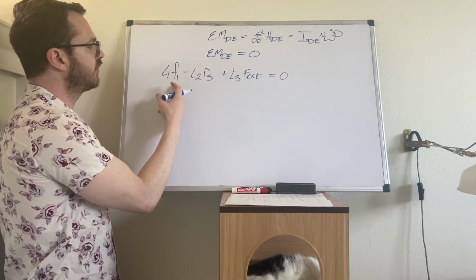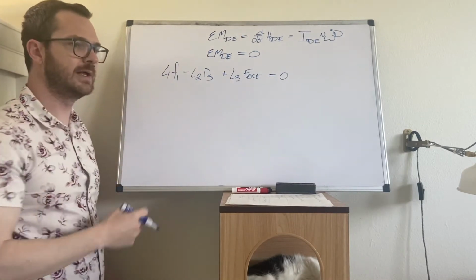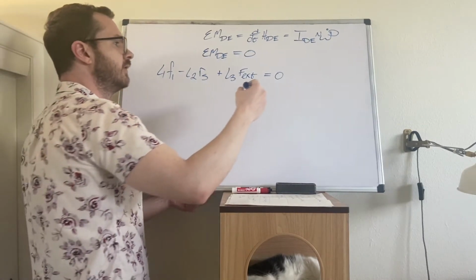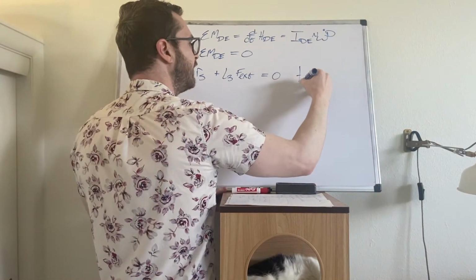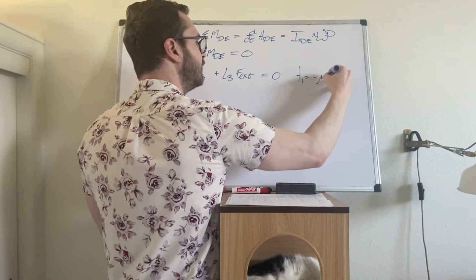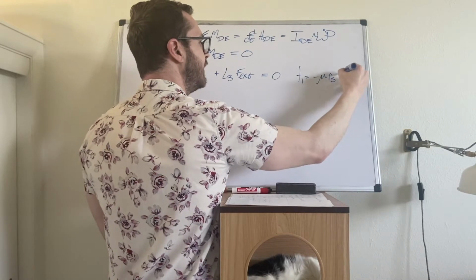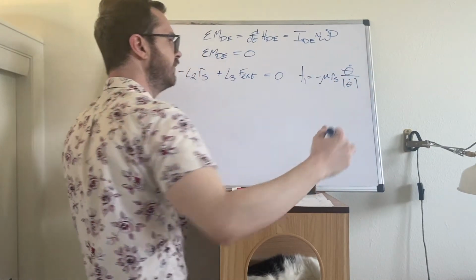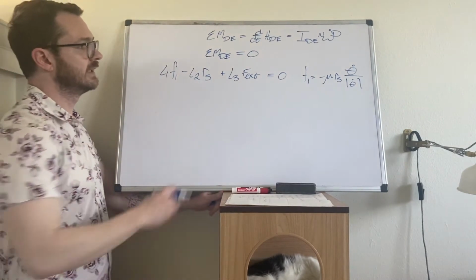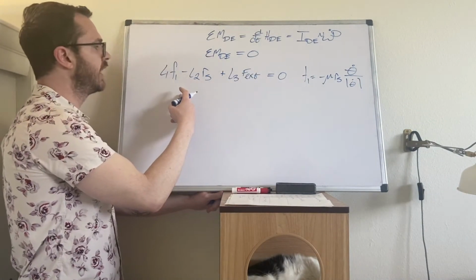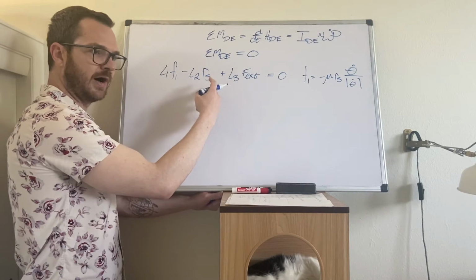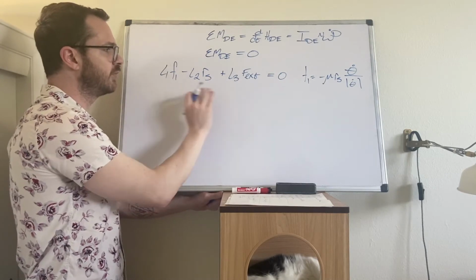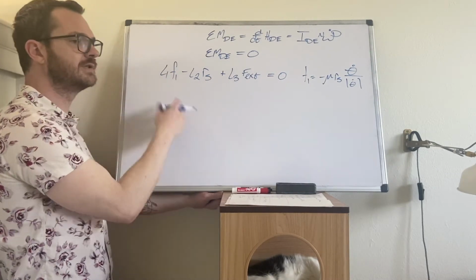Notice this equation has F1 in it, and we wrote a definition for F1. We said that F1 was going to equal minus mu R5 theta dot divided by magnitude of theta dot. So let's put that into this equation. Now we've got two R5s, so we group those R5s, move everything else to the other side of the equation, and solve.